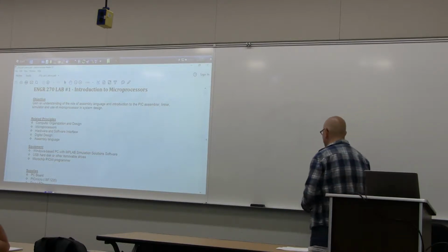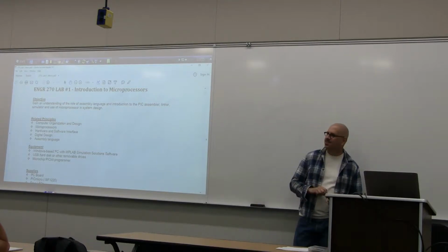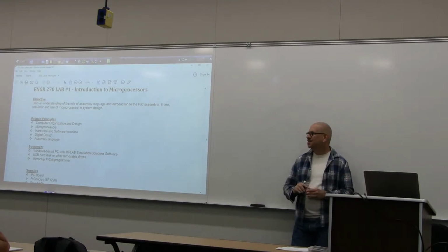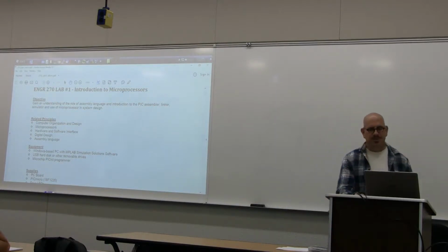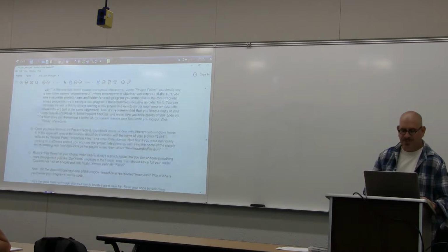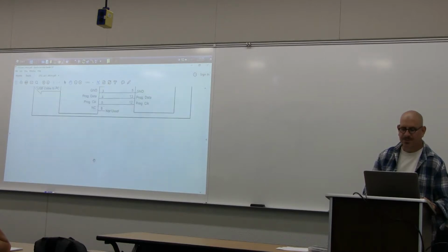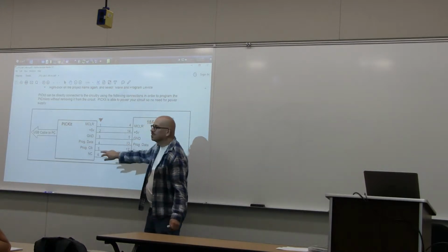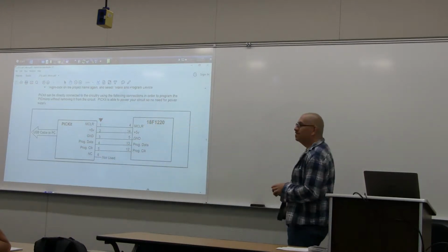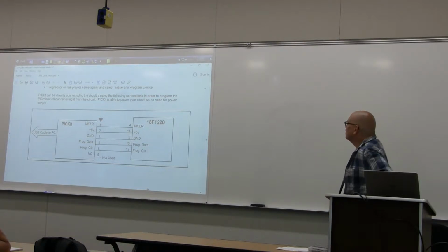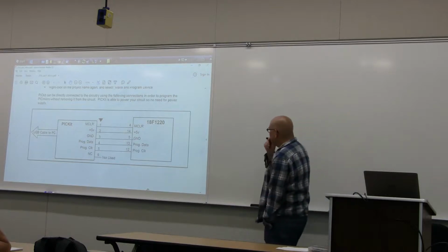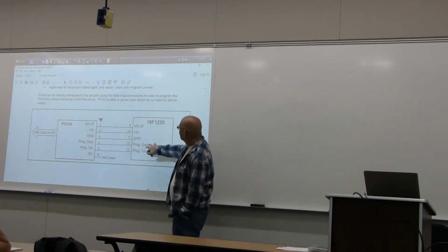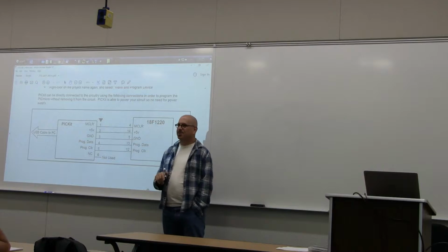If it says unknown device or expecting 7E and got 00, or those kinds of errors, it usually means something's wired incorrectly. Something between the PIC-Kit2 and the chip. So this wiring down here. And more often than not, these two wires have been switched. But it could be the ground and power have been switched or something else. So double check that.